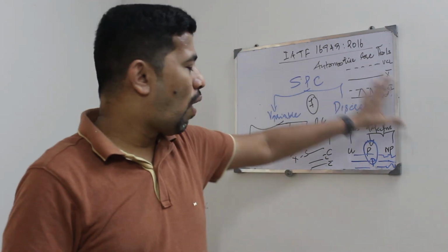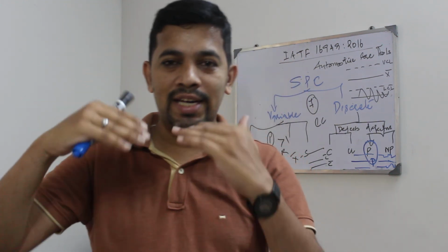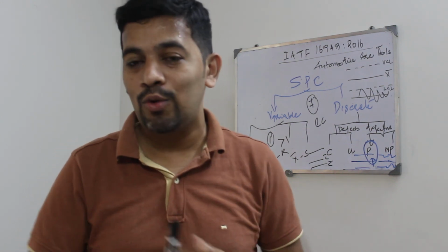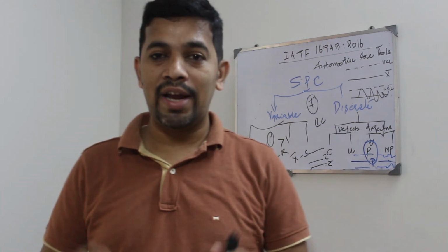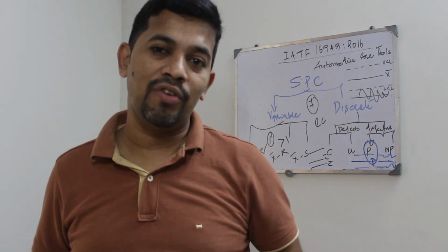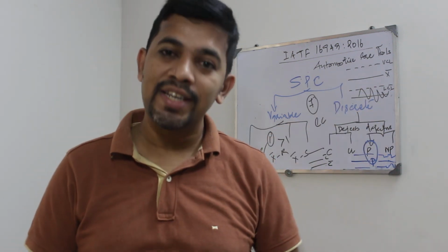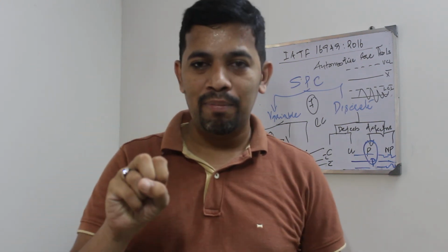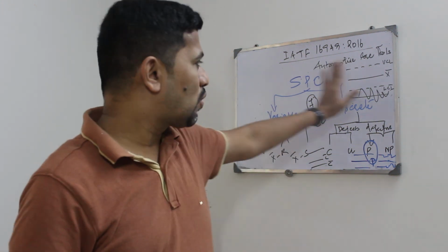So all to do with SPC there are 7 charts, and all charts carry limits. Those limits are calculated based on your samples, based on your N value. For example, let's say you want to talk about the IMR chart, again X bar, and then you have A2 times R. So the amount of data you have and all that, all the limits are calculated. It is not coming from the specification, it is coming from the process based on the constant value. The tabs calculate this, and you can do it in Excel as well. So this is all about SPC.